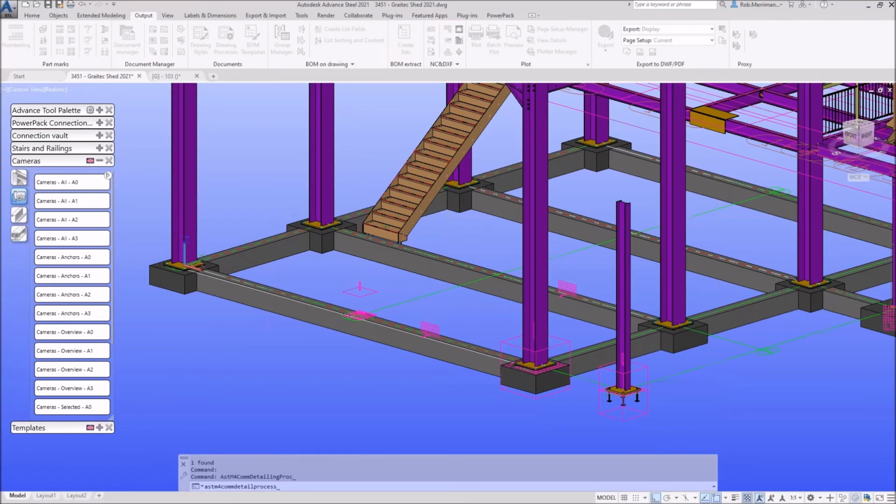And that will take us up to about the 45-minute mark, and then that'll probably be the end of today's webinar. So we'll run that stanchion layout, and just show you what else I've done in here. I've put my base plates on. I have named the joints because I will get given the base plate information from my connection engineer, and he will probably call them base plate 1, base plate 2, base plate 3. So for someone who's checking my model against the engineer's calculations, we want to make life easy for them, so I will use the same reference as my connection engineer.